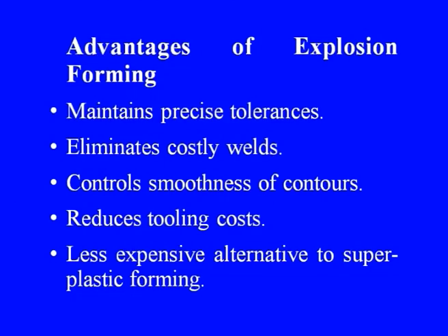Now, let us quickly look at the advantages of explosion forming processes. Number 1, it maintains precise tolerances of the work part. It eliminates costly welds, controls smoothness of contours, and reduces tooling costs. These processes are a less expensive alternative to superplastic forming.